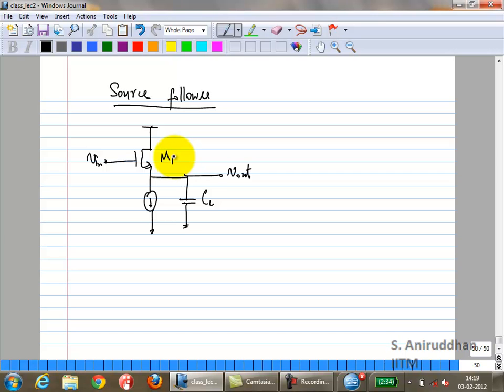So now again you have a capacitive divider here, right? Through CGS, now you have a capacitive divider. So again, it's not going to fall indefinitely. Okay, well and good. Now, what is the pole frequency going to be at? So now, assume that again this is driven by an ideal source.